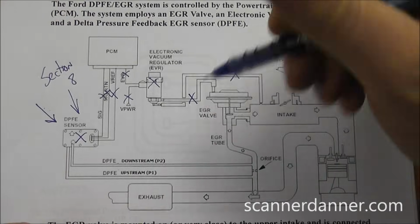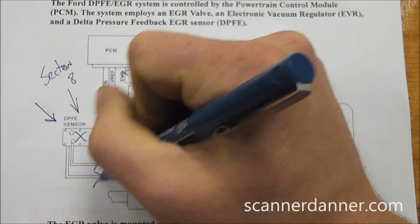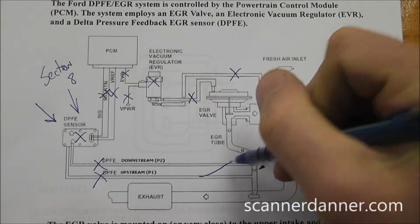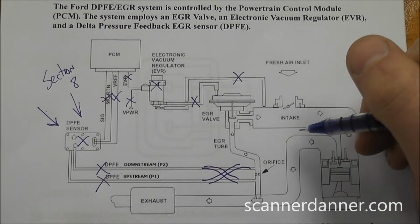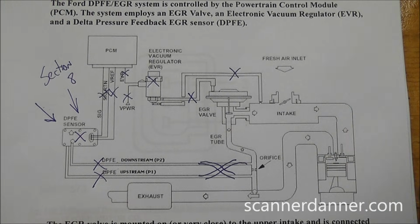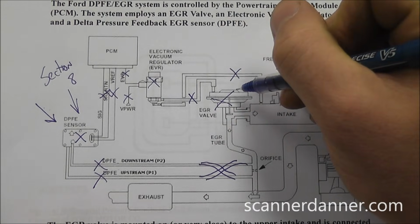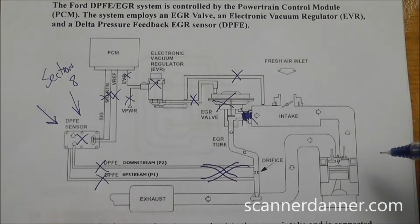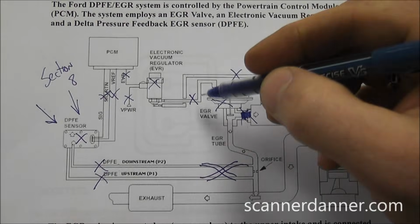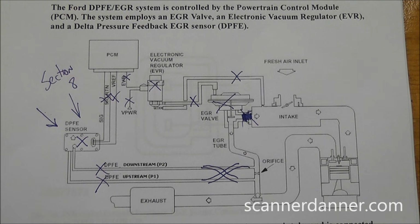Section 8, pressure sensors. We could have a supply issue to the DPFE on this upstream hose or the downstream hose. Actually, I've seen these where guys will switch them. This hose will be connected here, this hose will be connected here, and it goes crazy. When the EGR valve opens, it goes the other way around. It's kind of weird. We could have an EGR valve restriction, or the valve itself, or we could have an intake restriction right here as far as flow codes go. So you got 1, 2, 3, 4, 5, 6, 7, 8, 9, 10, 11. Really 11 or 12 different problems for an EGR flow code on a Ford.